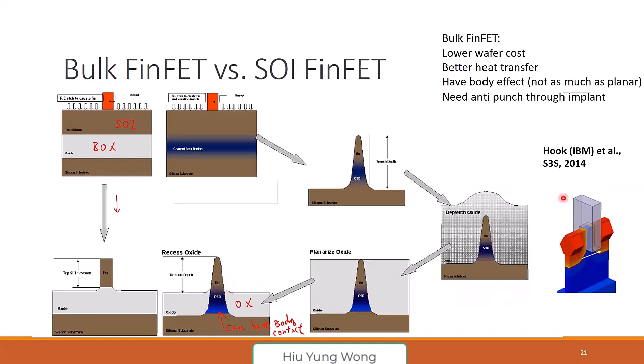So here we are doing a cut here. So punch through is here. The current can go from here to here because you have bulk. In SOI, they are blocked. But how do we prevent it? We just make this very P-type, then you have the PN junction to avoid them from punching through. So this is a 3D. Is that clear? Any questions?